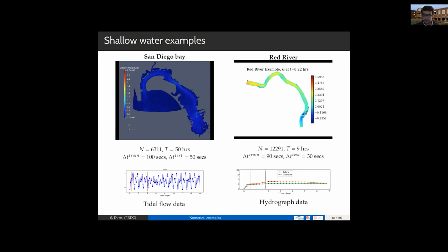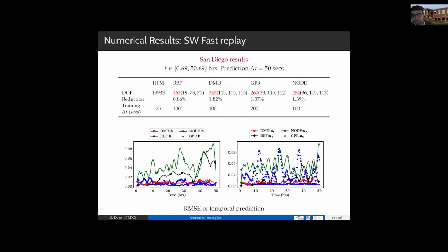So as you can see, there are some interesting artifacts with respect to localized flow features, helical flows and so on that happen at the bends of this particular model. And because of that and because of the advective nature of the flow, this particular flow actually doesn't admit a very efficient reduction in terms of the POD basis, because it has a very large Kolmogorov width.